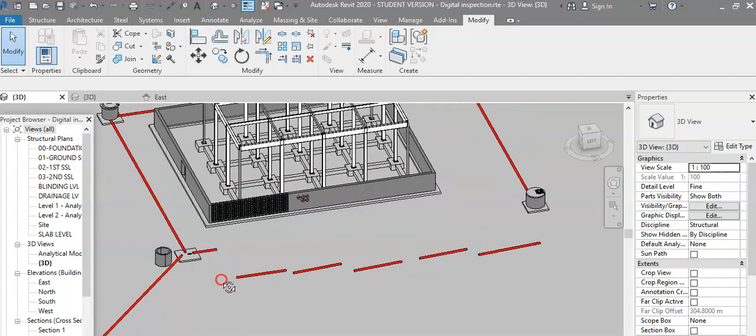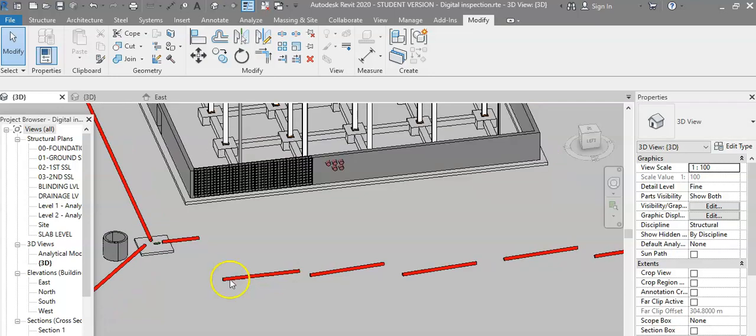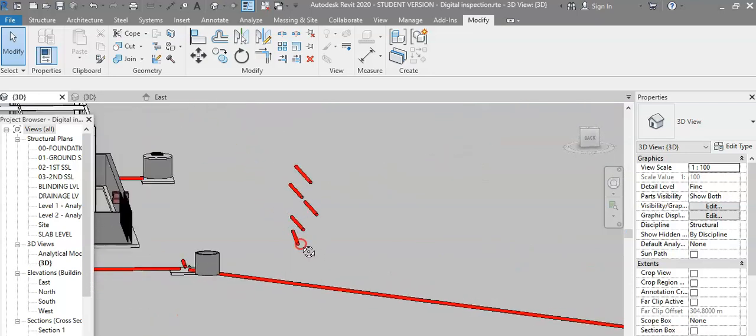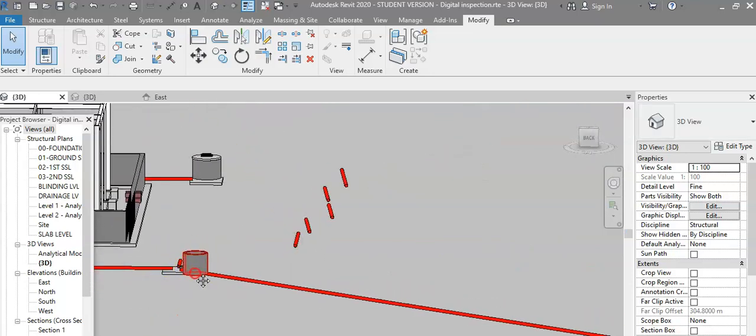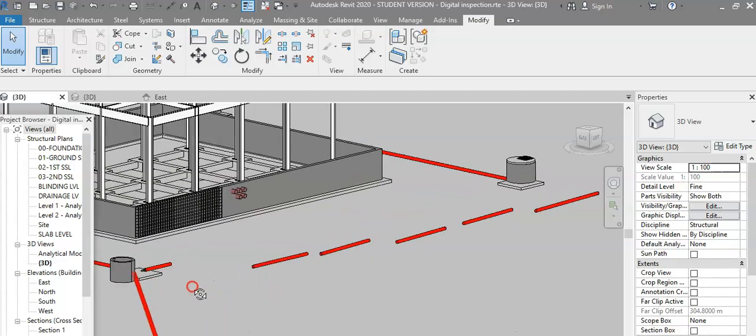Well, the procedure is, before the work starts, usually the team will bring all these pipes and lay them on the side of the line of the pipe. For example, we want to go from this manhole to that manhole. They lay all the pipes on the side there, ready for the workers to bring one pipe after the other and continue the connection.